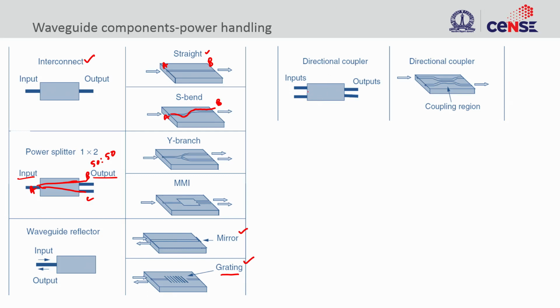The reason why it is called directional coupler is it couples light from one waveguide to the other waveguide only in one direction, let us say, right. So, the light from here could be coupled to the other without coupling anything to this, right. It is possible to realize such configuration, and that is the reason why we call it highly directional, right.